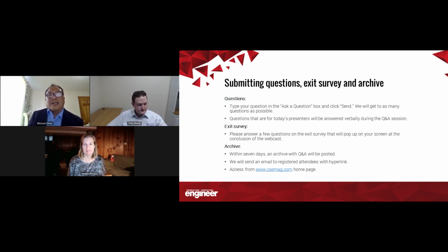That's a great question. So in Ohio, with state projects, we have to be able to show a payback analysis that whatever lighting fixtures you're putting in, there will be a 5-year payback analysis. So what is included in that calculation? You'll have to find out the cost of energy, who the power company is, and typically find out from the owner what rate they're paying.